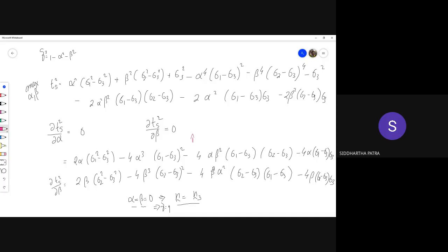So we can divide either side with alpha, and also in general sigma 1 is not equal to sigma 3, so I can always divide either side with sigma 1 minus sigma 3. That is not true in general, but of course there can be a situation when all the principal stresses are the same, or at least two of them are the same. It's a possibility, but in general you can say that is not true. And we are talking about a general situation here.